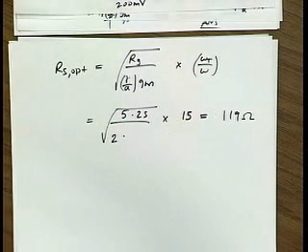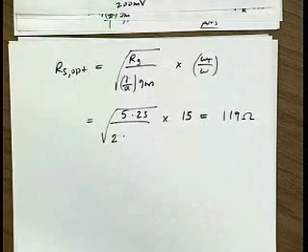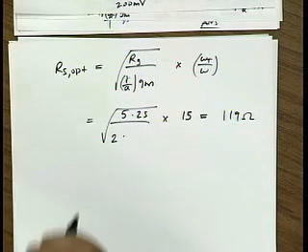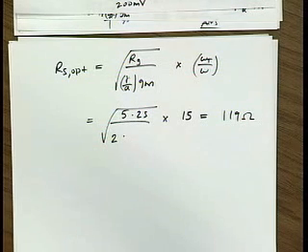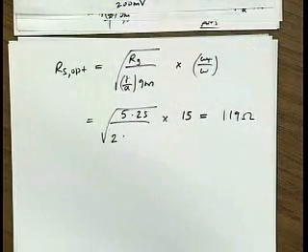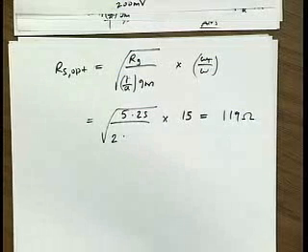Yes. The Fmin equation earlier, over which frequency did that equation hold? From DC to omega t, or? Yeah, certainly not till omega t. Also, probably, if I had to give a conservative estimate, I would say omega t over 10. But you can probably use it up to omega t over 2, and it's reasonably valid. Doesn't omega t depend on GM? It does, yeah. Usually when you put the device in strong inversion, so we're making some simplifying assumptions here. Okay, any other questions?